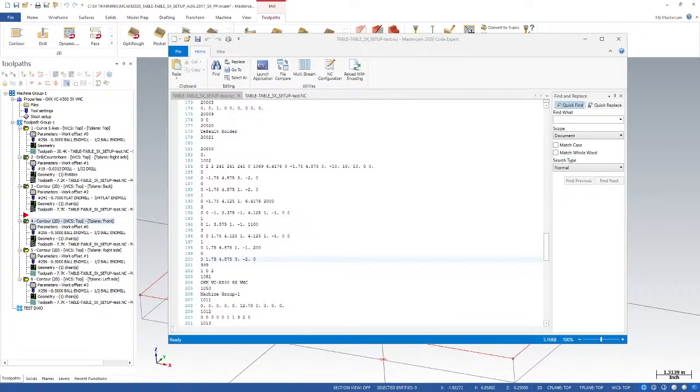I mean, that's really the big thing, is part of the benefit of making any part on a 5-axis machine is the fact that you can accomplish multiple cuts from different angles, using the same or multiple tools to try and perform as many of the operations to cut the part as possible on that 5-axis machine.